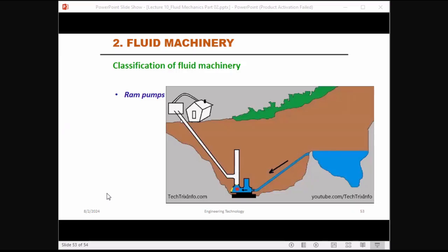The flow of water from the pool uphill is getting into the ram pump and the pressure increases inside the ram pump, which results in the water moving up. So you can see the delivery valve opens up and the water moves upwards and it still continues to move upwards, which pressurizes the air inside, and due to the pneumatic pressure you can see it further get pressurized to a particular level and then that pressure acts back on the water.